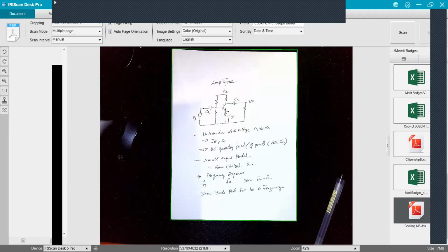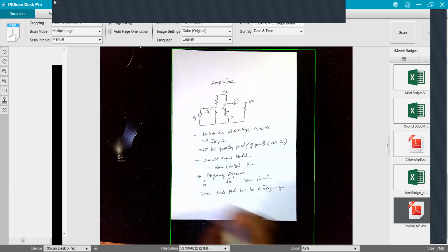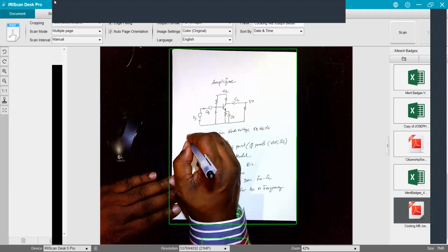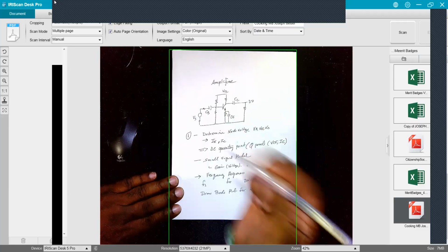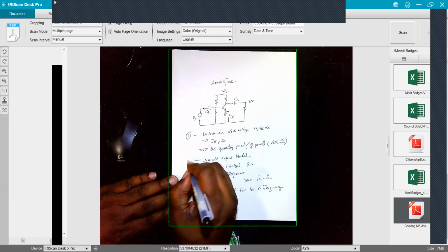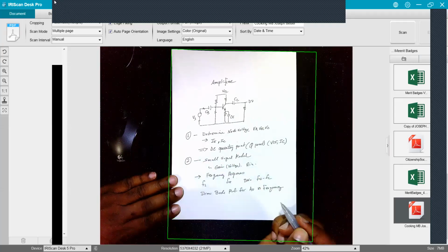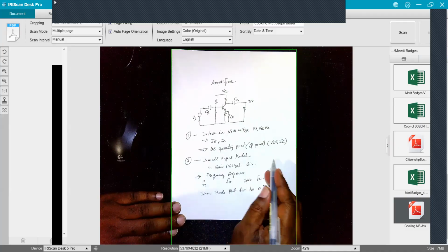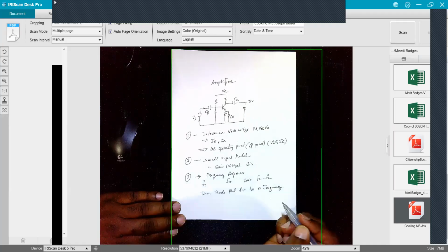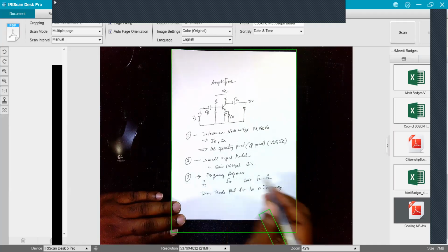So how do you get all this? Number one, these are the steps from your circuit, in that order. We do this, and from this we get the DC stuff. We do our small signal model, get our gain, our input impedance, whatever, and then from that we can calculate our poles.